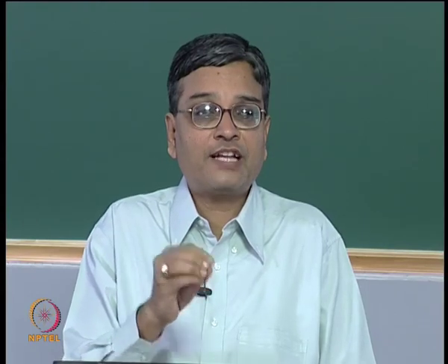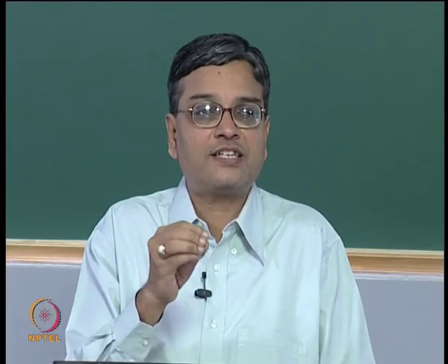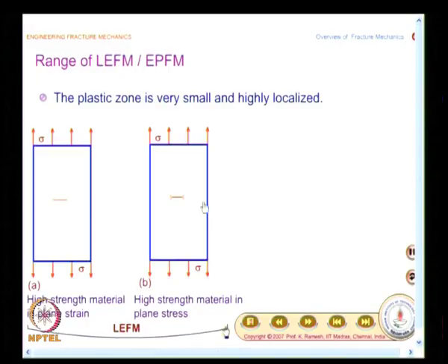I mean, when you apply the load, it will have elastic response, it will not have a plastic response, but near the crack you will have a plastic zone, and that plastic zone dictates how the crack is going to behave. And in fact, in fracture mechanics, if you have some plasticity near the crack tip, it is beneficial, it prevents the crack to grow easier. Okay. So, it is good from the point of view of safety.